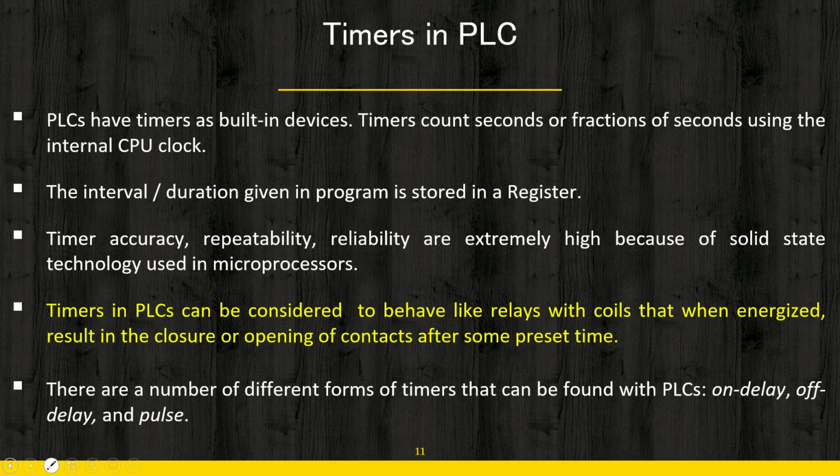Now let us start our discussion on timers that are available with PLCs. PLCs have timers as built-in devices, an inbuilt facility. You need not connect any external or additional unit to the PLC to have this facility. They are always inbuilt. Even the smallest brick type PLC will have a timer inbuilt into it.